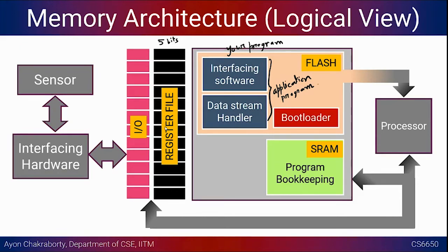So you have to know that if you are reading from that particular memory location, you are actually reading some sensor data. That's how it's all organized. There is a direct mapping between the input output lines and portions in the memory, and we will see the functionalities and so on.